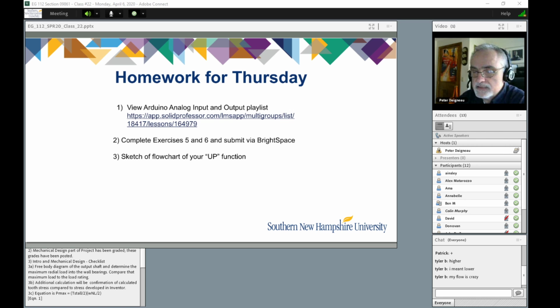The other thing I'll say is that the other library that you're going to need access to is the servo library, because you'll use that library to drive your system via the PWM levels. So I believe you'll need to have a hashtag include identifying the servo library up top in your code so that you'll be able to do the functions that are necessary. And again, I'll try to get some more information on that on Thursday. Okay, so everybody's good. Give me an agree.